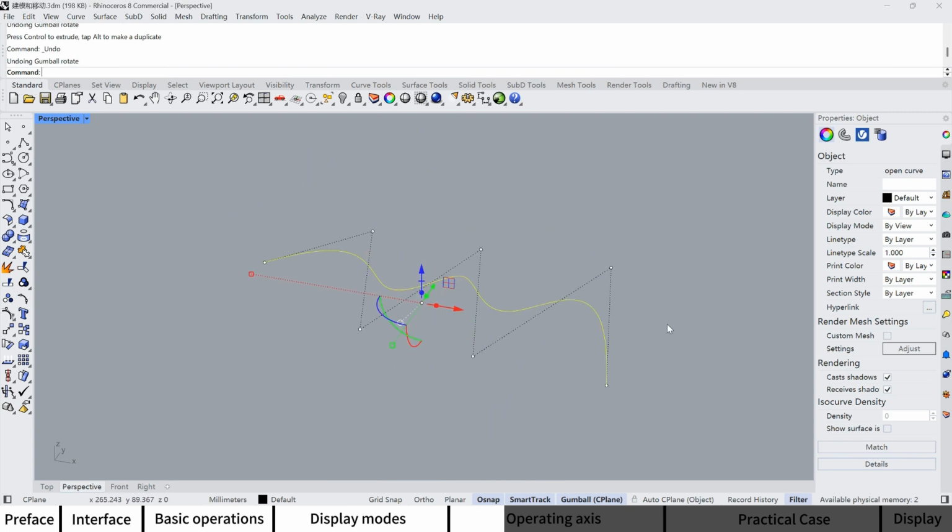Now, here's a cool feature, the little square. When you change your view, you'll see three different colored squares pop up. These squares correspond to the other three 2D views. If you click and drag one of these squares, you can move objects on that specific plane. It's like you're working in the other 2D views, but all within the 3D viewport. For example, if you drag the red square, you're moving the object in the XY plane, just like you would in the top view.